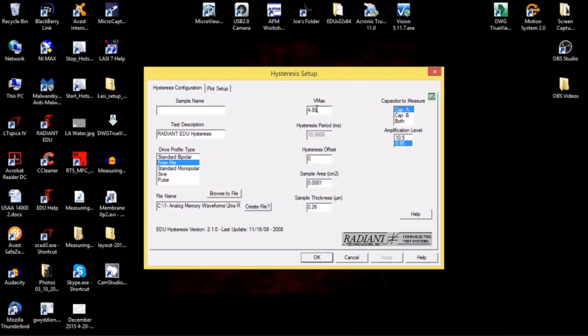The EDU has 300 or 330 ohms of output resistance. The voltage drop across that from 4.89 volts will result in 4 volts at R1 when I'm using a 2200 ohm value for R1. None of these other controls matter, and you shouldn't change them.